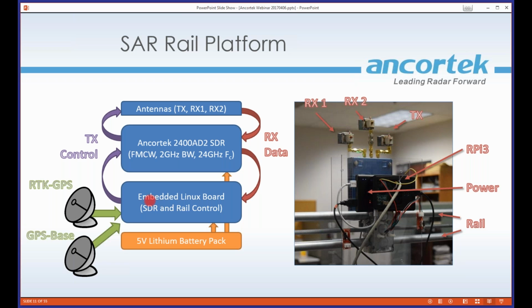Now, to make this work outdoors pretty well, what we've done is we've set up an RTK GPS system. So you don't see it in this picture; it'll show up later. But we have an antenna that we mount on the top here to give us pretty good GPS information and phase carrier measurements, and we correlate that with a base station we have out in the field. And then also, I don't know if any of you are familiar with CORS, but it's a nationwide service where you can get GPS correctional data to improve your own collections. So we have those two feedback systems help out our radar, so we can get a couple centimeters of resolution when we're out in the field, which is outstanding for a moving platform.